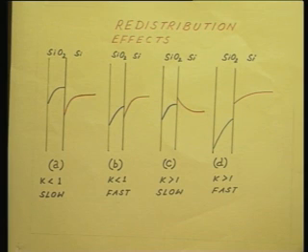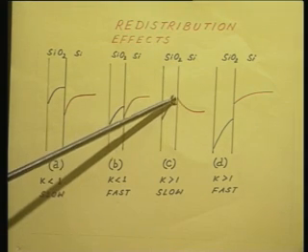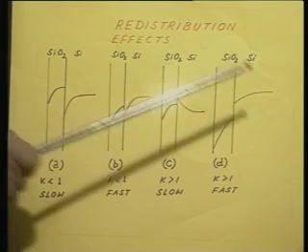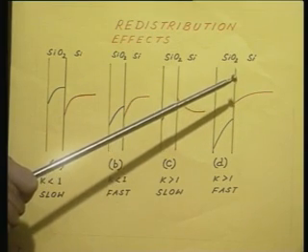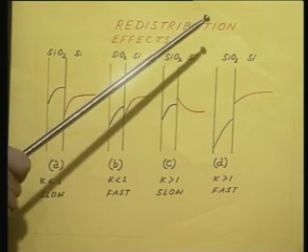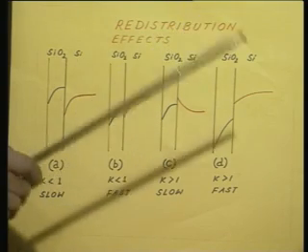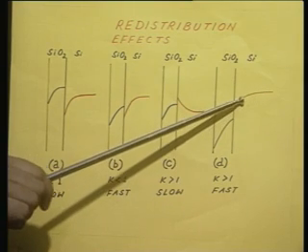You see, gallium has a segregation coefficient greater than 1. So, what should you have expected? You should have expected a pile up at the silicon-silicon dioxide interface, isn't it? In the phosphorus case, because K was greater than 1, you got a pile up. So, even in case of gallium, it stands to reason that since K is greater than 1, I would expect a pile up of gallium at the silicon-silicon dioxide interface. Instead of that, you see, if anything, it is falling.